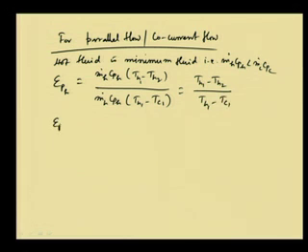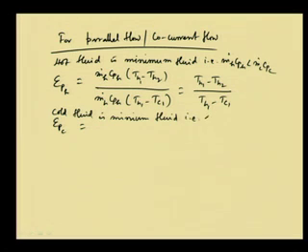Similarly, we can have epsilon P for the cold fluid, when the cold fluid is the minimum fluid. So, I will write here parallel flow case and cold fluid is minimum fluid. So, we have 2 cases, that is here m dot c Cpc less than m dot h Cph. Mind it that both the cases we are considering under parallel flow or co-current flow situation.